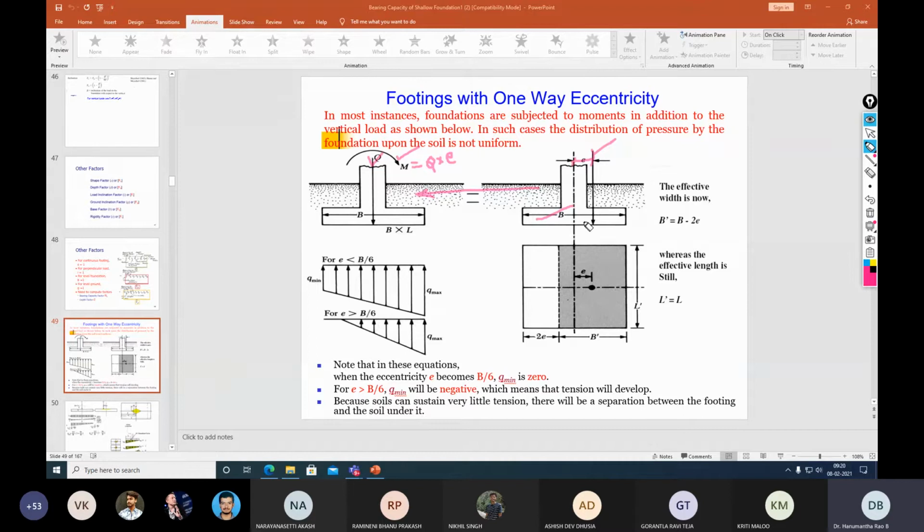In reality, the footing is subjected to an eccentric axial load, but when it is converted for mathematical simplicity, the column is again at the center, and the eccentricity is accounted for in the form of a moment. However, though there is a mathematical simplification or transformation from reality to the mathematical form, in terms of the soil bearing pressure, there is a change.